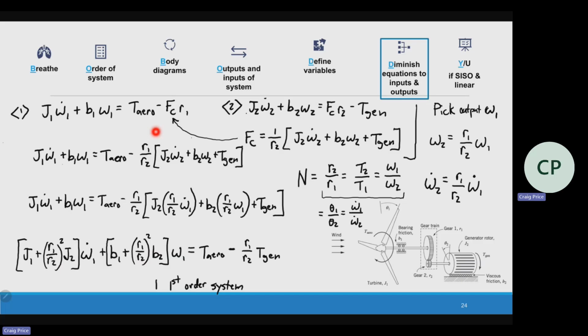So if I know these values, I can figure out what the speed is. If I'm trying to figure out what my moment of inertia is, how much mass that turbine is going to be, I can easily plug that in to see how that affects what's going on here. What is our motion going to be? We don't want to go too fast. We don't want to kill too many birds, right? We want it to go a little slow, so maybe we add some mass here. We see how that affects the acceleration and velocity.